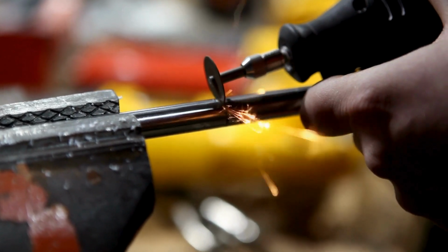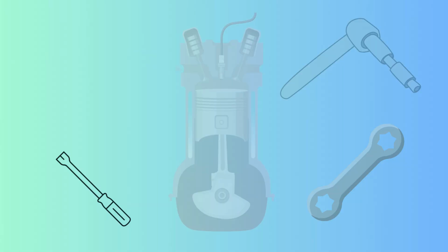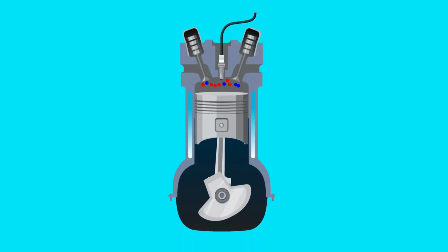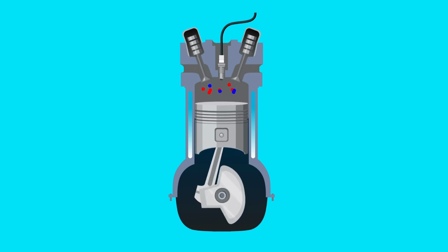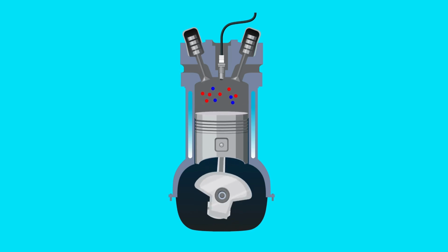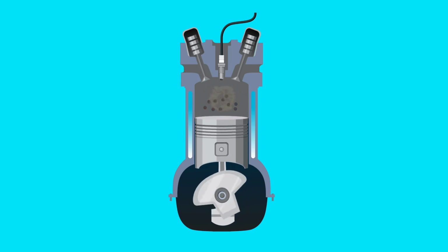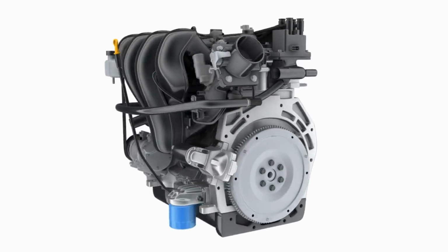In internal combustion engines, torsion refers to the twisting force, or torque, generated by the combustion process and applied to the crankshaft. This torque is a crucial aspect of how the engine produces power, converting the reciprocating motion of the pistons into the rotational motion needed to drive a vehicle. Torsional vibrations, a form of these twisting forces, can also arise in the crankshaft and other engine components. Crankshafts, present in internal combustion engines, are mechanical parts subject to torsion and bending that vary over time and, if the forcing is close to one of the natural frequencies of the system, they can encounter problems of torsional oscillations.